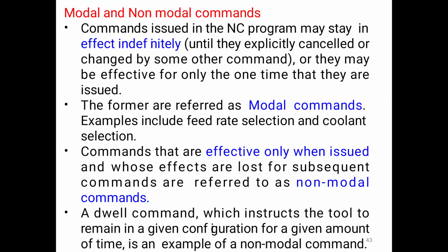The commands that are effective only when issued, and whose effect is lost for subsequent commands, are referred to as non-modal commands. A dwell command, which instructs the tool to remain in a given configuration for a given amount of time, is an example of a non-modal command.